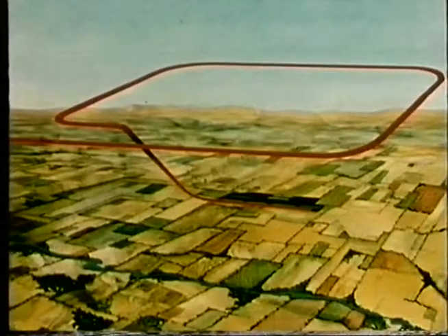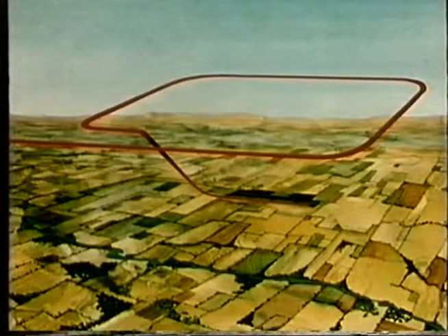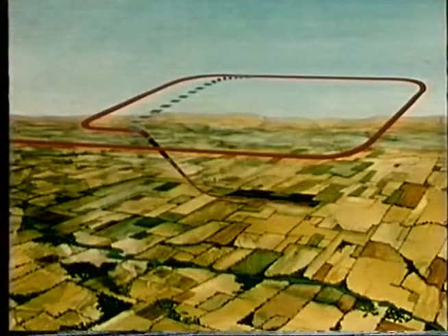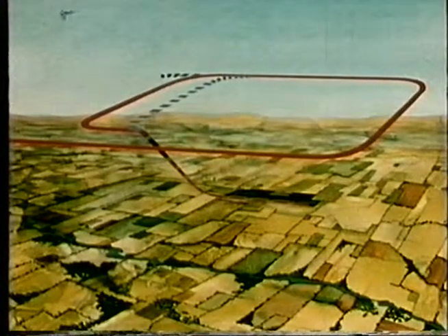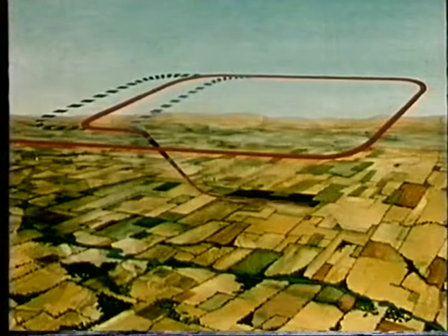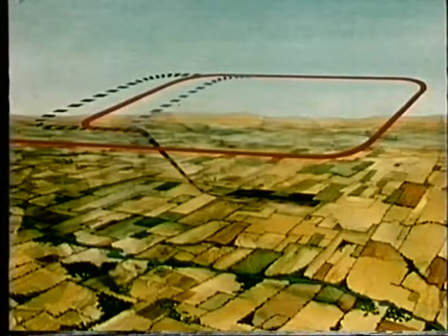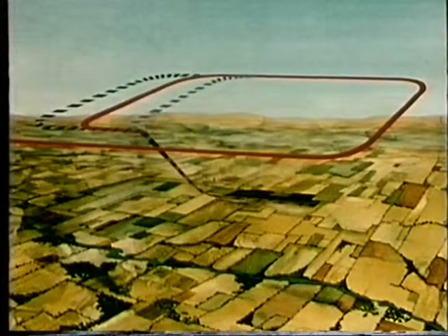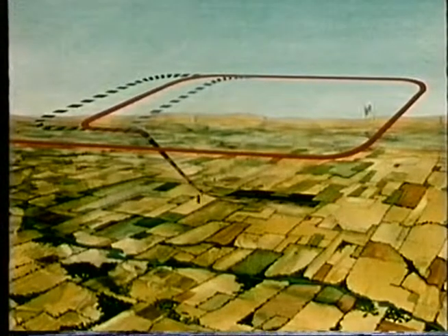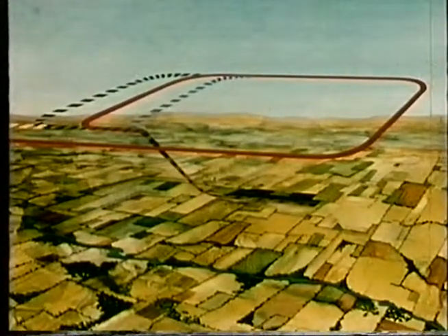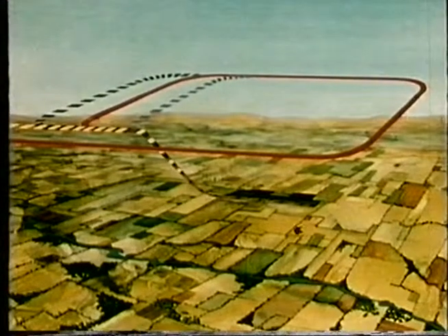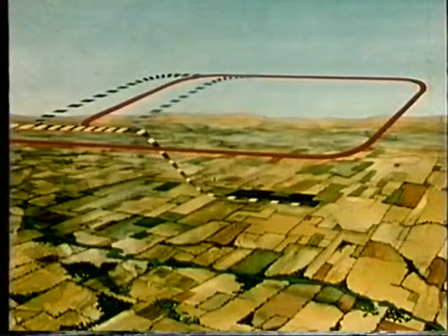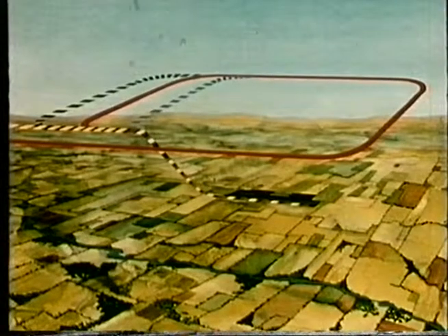If it becomes obvious to the aerodrome controller that the correct spacing is not being achieved, he may instruct an aircraft to "make short approach" or "make long approach" when on the downwind leg. Instructions such as these are issued to ensure that aircraft arrive at the beginning of the runway with not less than a minimum separation. If traffic conditions permit, an aircraft may be cleared for a straight-in approach. The aerodrome controller determines the landing sequence from the relative position of the aircraft in the traffic circuit.